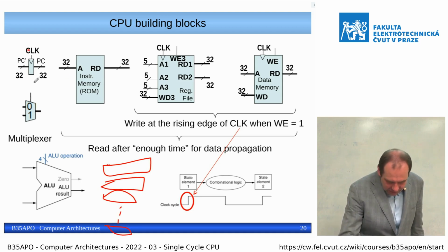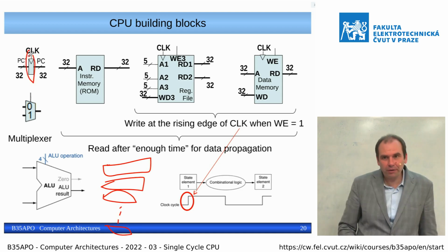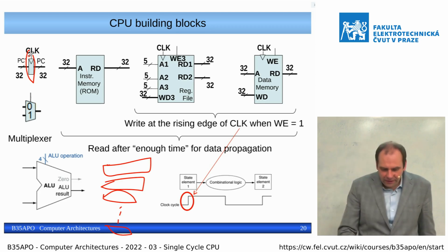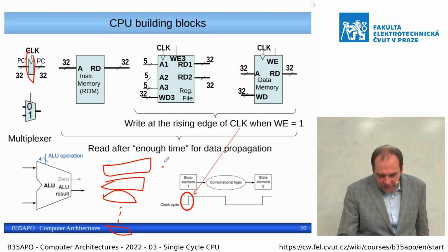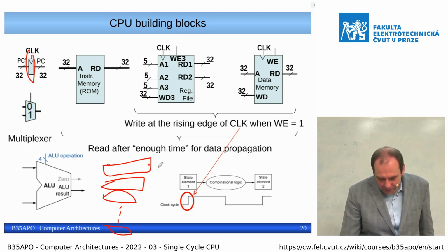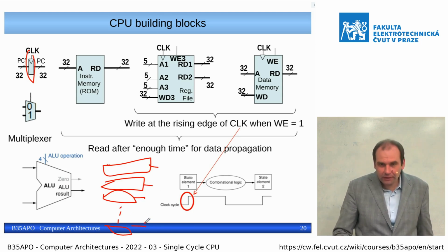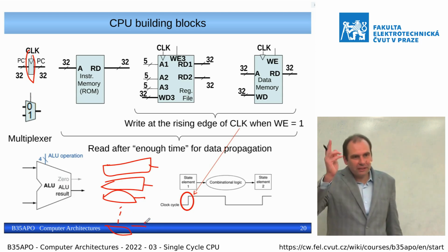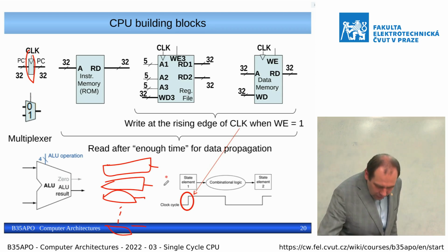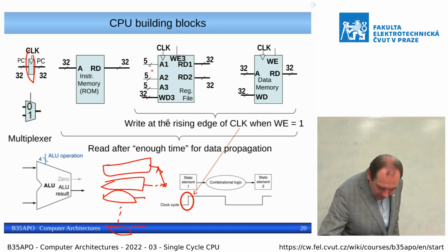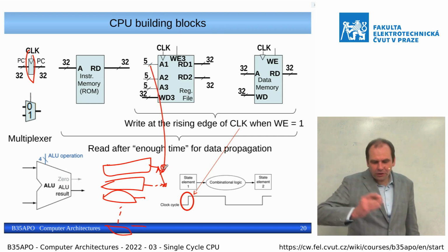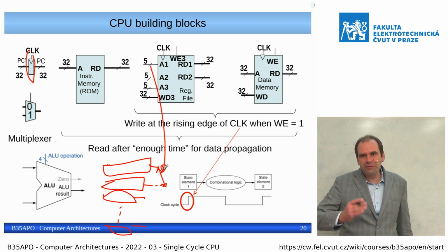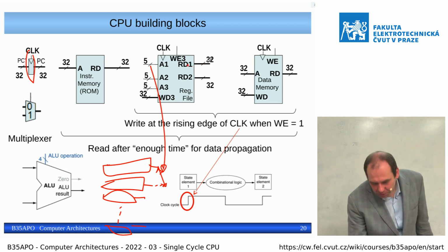As is this single register here for the program counter. And each of those registers can be addressed by 5 bits to be read. So we have there 32-bit values, and we have there a multiplexer which selects according to this 5-bit value from which of those 32 registers we want to read data to a read port.